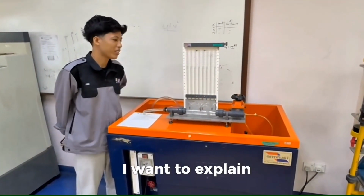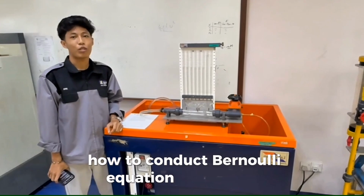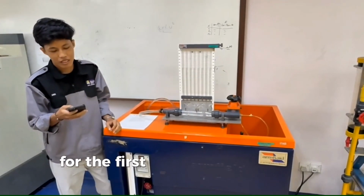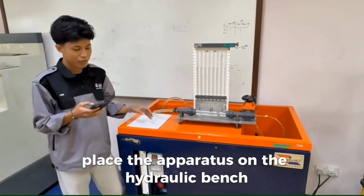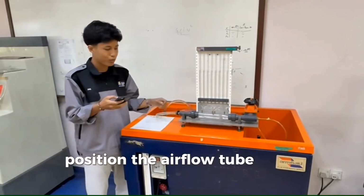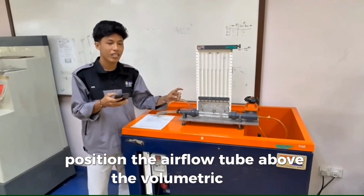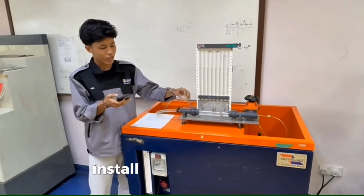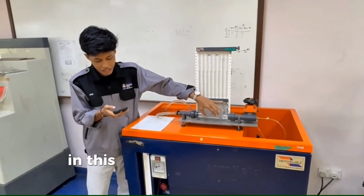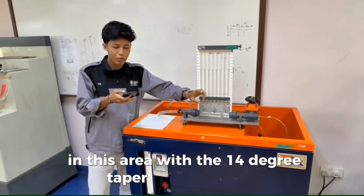Today I want to explain how to conduct the Bernoulli equation experiment. For the first step, initial setup: place the apparatus on the hydraulic bench, and position the outflow tube above the volumetric tank. Second, installation and water filling: install the test section in this area with the 14-degree taper facing the flow.